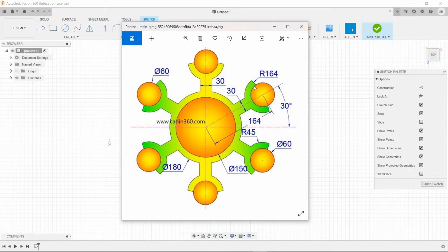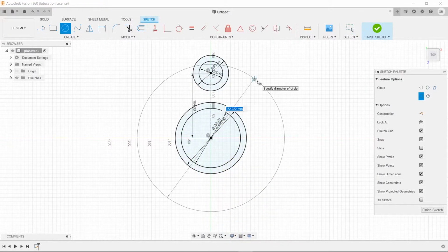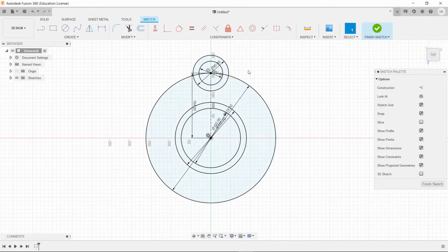Now, what's this 164 for? What does that mean? Well, if you look at it, these are not cut perfectly straight across. I'm assuming they used a circle, brought it out to here, and that circle has a diameter of 328 millimeters, and that's what's causing these cuts, because you see they're angled a little bit. So we're going to do that. We'll type out a circle of 164 times 2 and press enter.